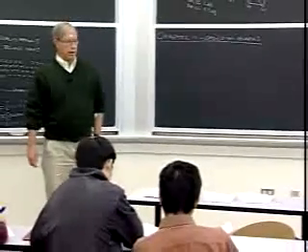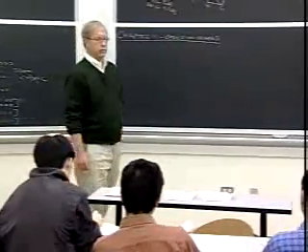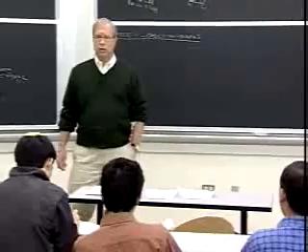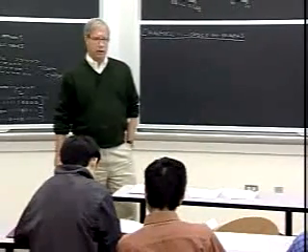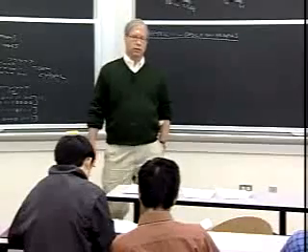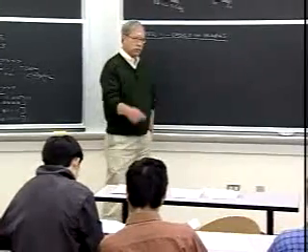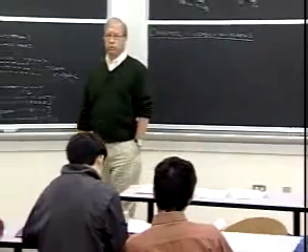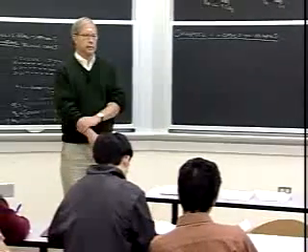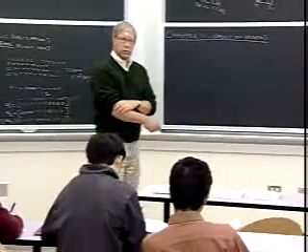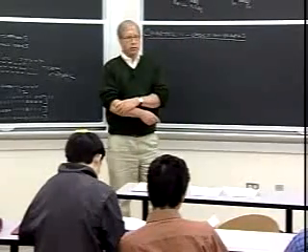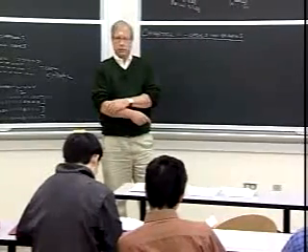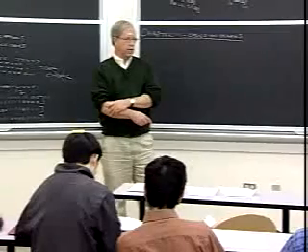Or now we have this trellis representation, which certainly looks like a more graphical representation. It certainly characterizes the code in a very direct way. What does a trellis do? It basically displays all the code words on a graph. All right, there's a one-to-one correspondence between the set of all paths from the root to the end node in the graph and the code. So that's another way to characterize the code.